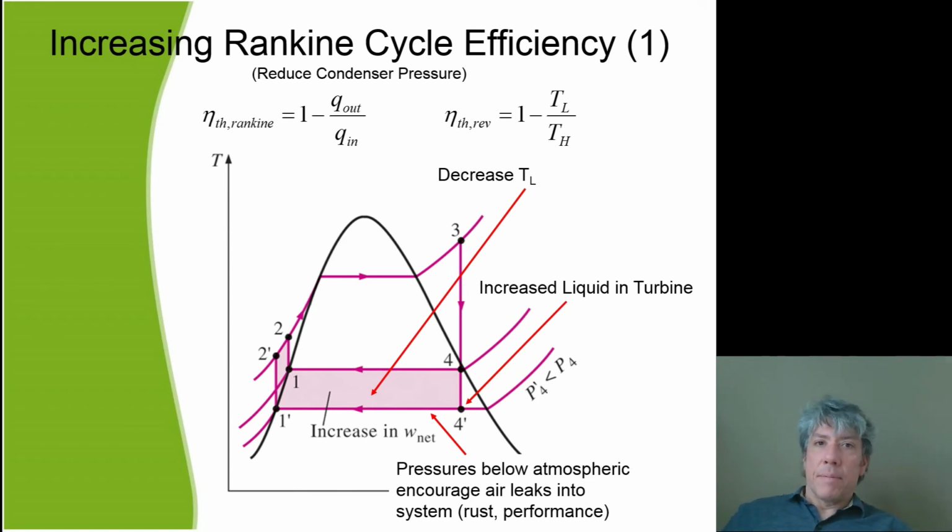But we wouldn't detect it, because the direction of flow would be from outside to inside of the process. And as this is running constantly, we would never see the leak. And so we would end up with oxygen in that very expensive liquid, and what would happen is exactly what we don't want to happen, right? All of this system would just rust. We wouldn't know about it potentially unless there's some way to sense it. And we'd have scrap metal on our hands instead of a power plant.